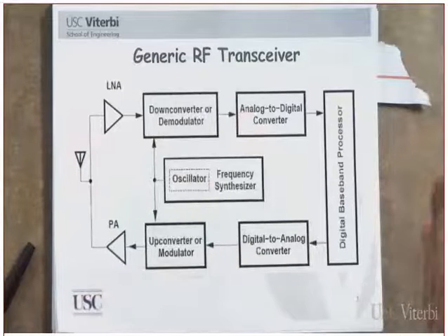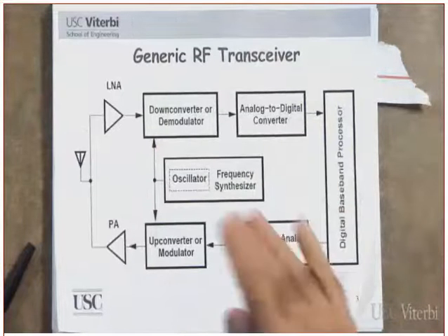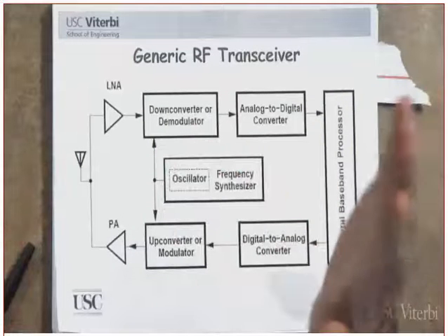We shape the pulse. For example, GSM uses a modulation technique that is called what? GMSK. And the G stands for what? The Gaussian shaped minimum shift keying. Do you know the Gaussian? How does it look? Sharp edges or smooth edges? Smooth edges, which means what? Its spectrum will become what?